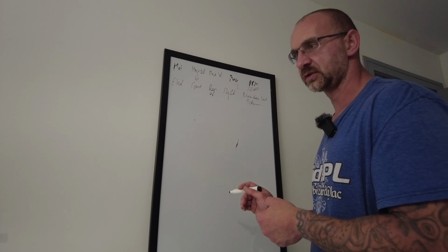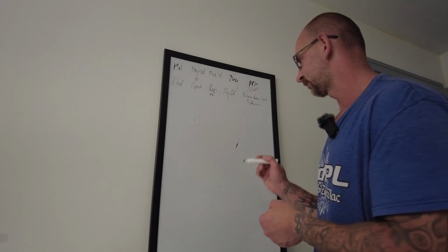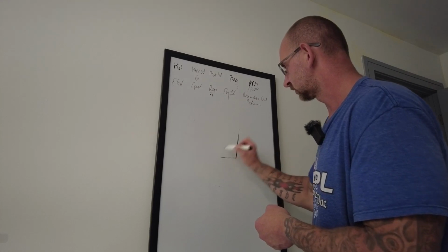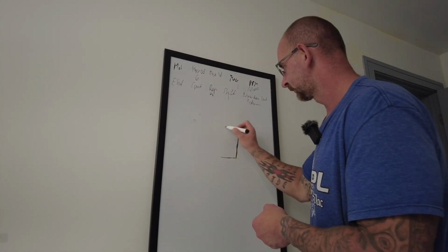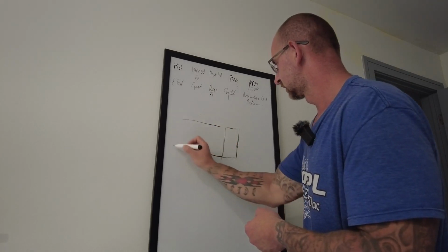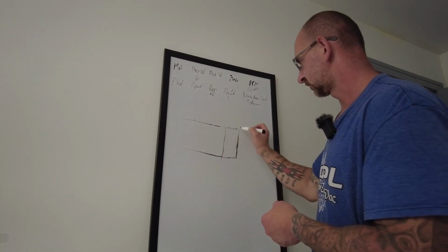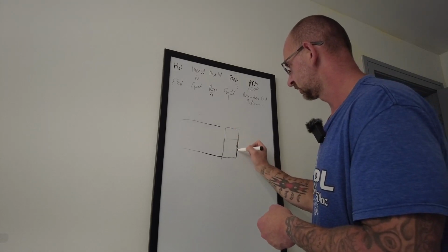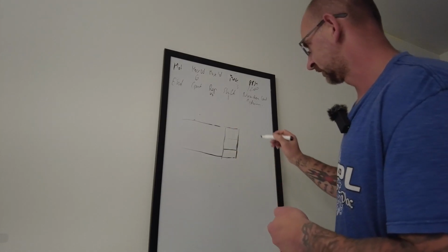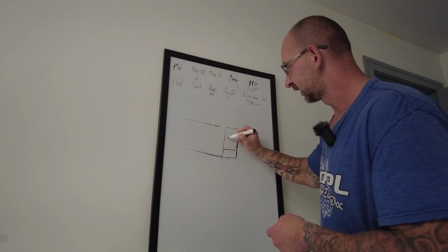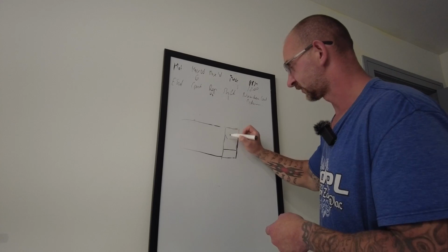Everything was running good, but for some reason on the last part, and my part looked like this, I was doing a ring job, like I said, out of big bar. So I did facing, OD turning, then I would come in with the drill, and then with a 35-degree bar, throw in the chamfer, finish the bore, and then do a chamfer in the back.